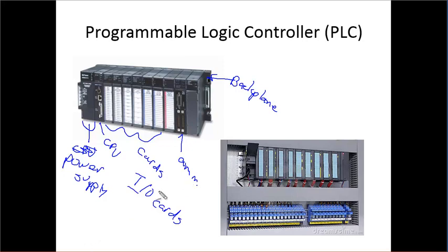If you have a communications card in here, and we'll talk about that a lot more in our next lesson, maybe you've got things like smart meters or some sort of smart device where the I/O, the actual A to D conversion, is happening in the device, and then it's got some sort of digital communications bus that can connect to the PLC.